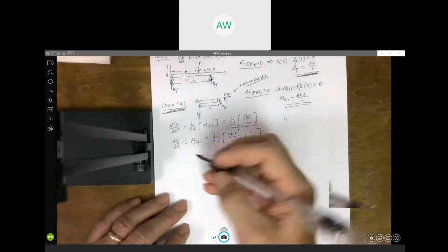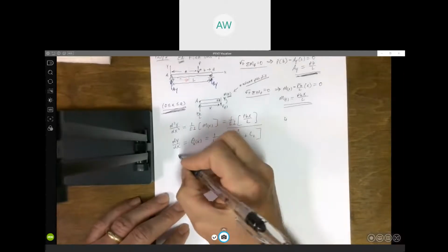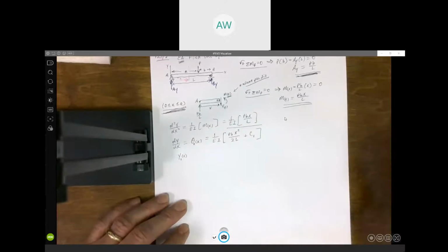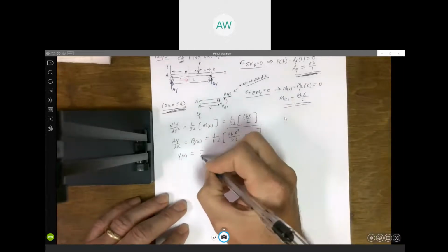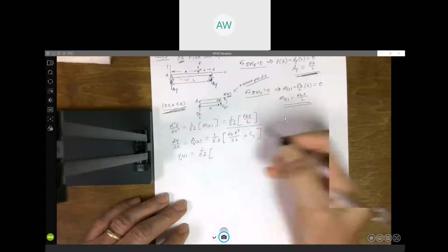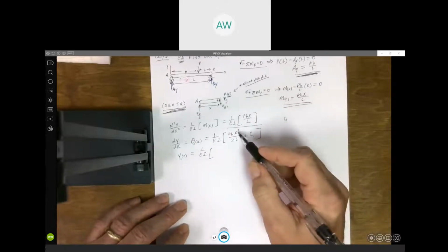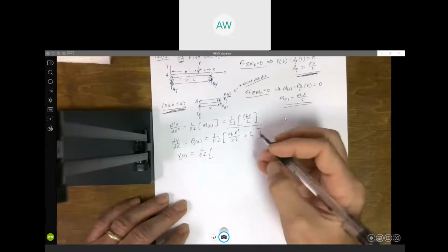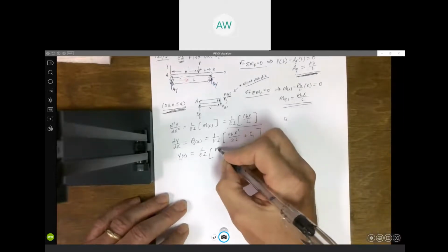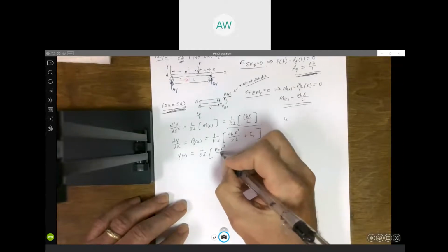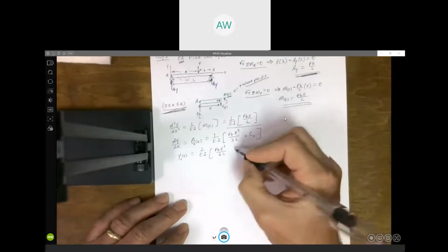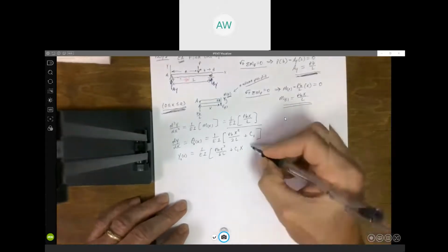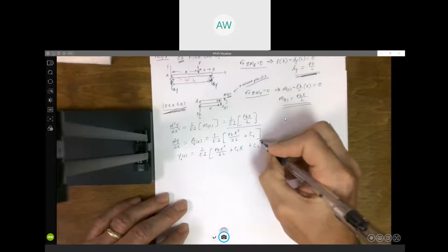And now we integrate again. So we integrate dy/dx, we get just y of x, and again, I'm going to denote this as y1. We get 1 over EI. Integrating with respect to x, we're going to get x cubed over 3 times 2, would be 6L in the denominator. So Pb x cubed over 6L. We've got a constant. We integrate that with respect to x, we just get the constant times x plus a second constant of integration.